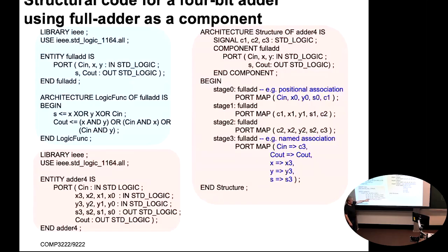It's got the 4 bits of the output, and it's got a carry in so that we can chain 4-bit adders together, and a carry out so that we can chain 4-bit adders together. As to the architecture of the 4-bit adder, we want to use the full adder component, and so we have to declare that in the declaration part of the architecture.